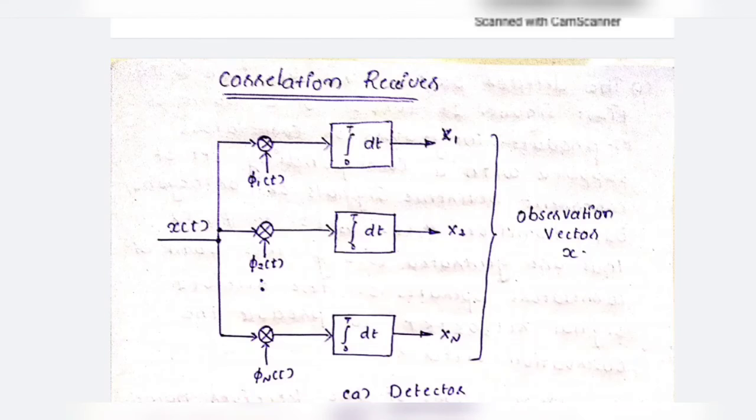Correlated signals, however, produce components near zero frequency that give a steady deflection in the output of the multiplier. In addition to their use in radio interferometry, correlation receivers are also used to reduce the effect of interference and of changes in the gain and other parameters of the system.